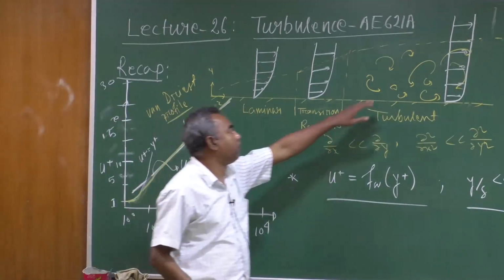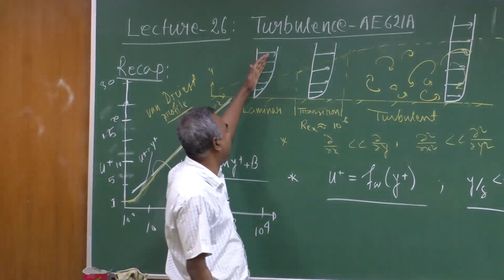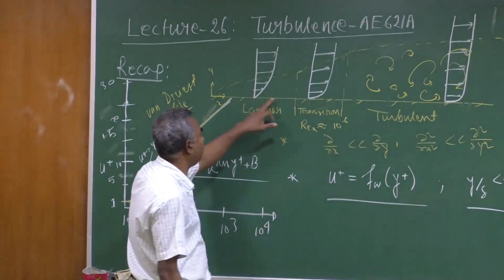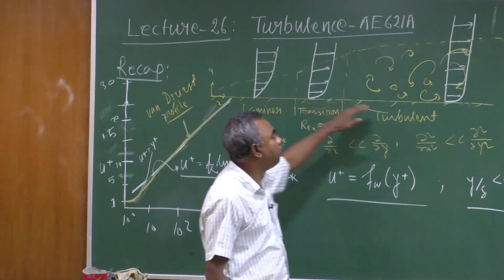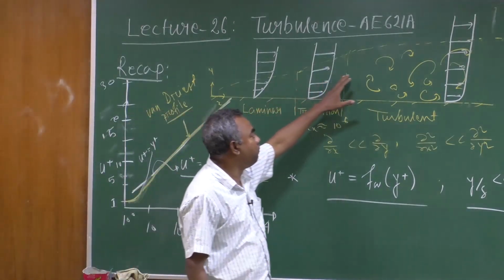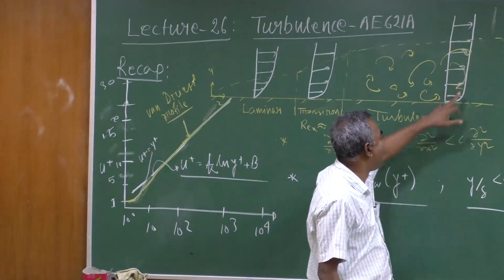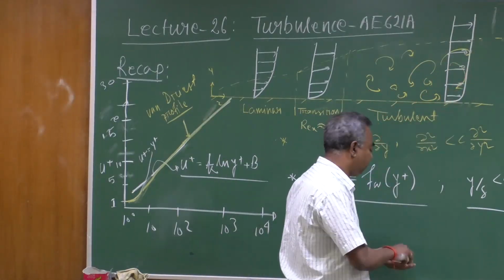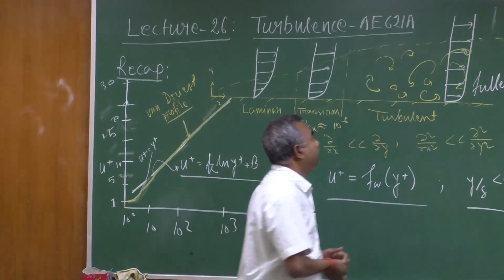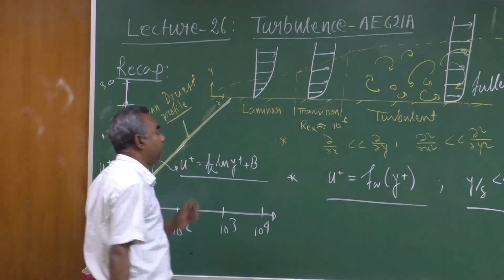So, the turbulent flow we are talking about here is a bit high Reynolds number flow, and if you see the velocity profile in the laminar regime, it will look like that. Then slowly as you go in the downstream direction, the profile will slowly become a fuller type of velocity profile. That is all because of the high level of mixing in a turbulent flow, the profile will be flatter or fuller, okay. So, this is known as a fuller velocity profile, mainly due to turbulent diffusion or mixing, okay. Please do understand this, okay.